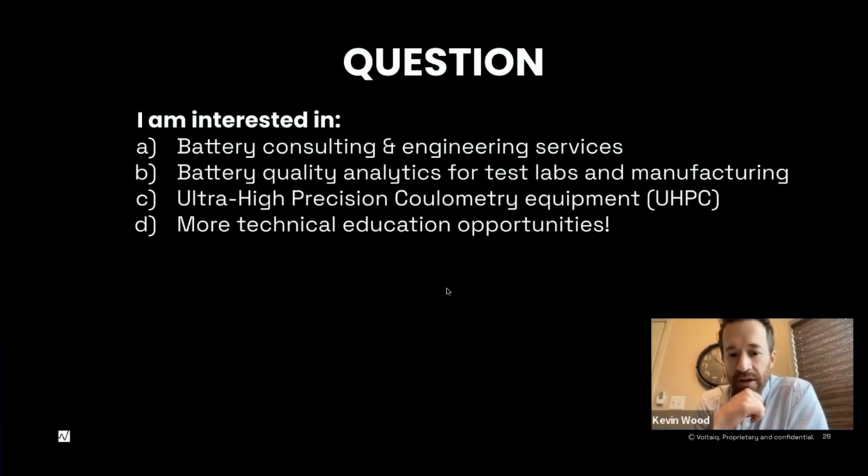So there was another question here for DQDV and real world vehicle data. You can go ahead and plot it. You can do anything. In the real world, right, your current is really changing all over the place. I think there's potential to do DQDV or potentially SDQDV or something like that during your charging step, but during discharge where it's all over the place, I would say that the value of that is going to be significantly limited. Something you just have to consider there. But that charging information of in-field data is actually a really great place to get a lot of good information, and I don't think that we're doing as much as we can do with that information right now.